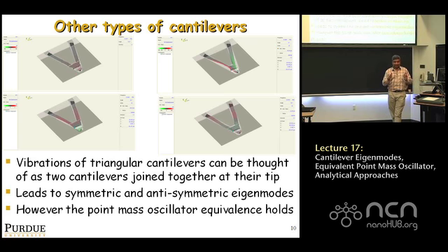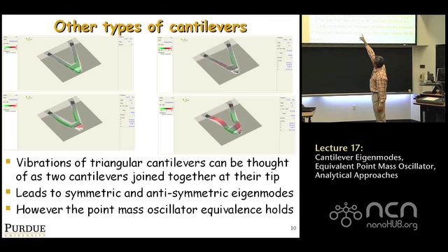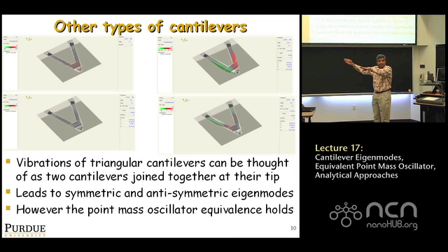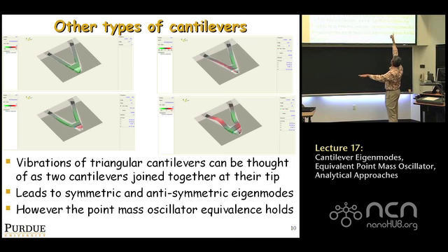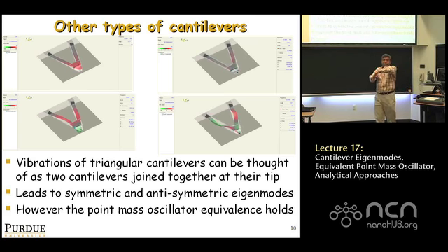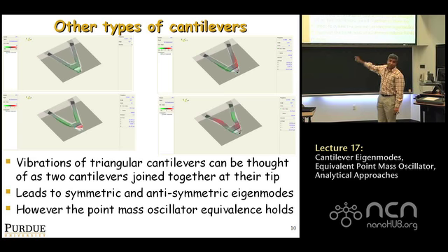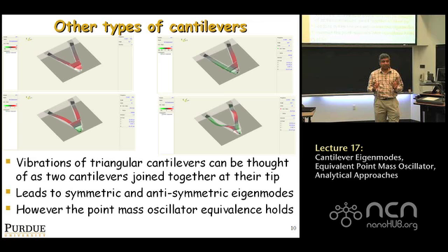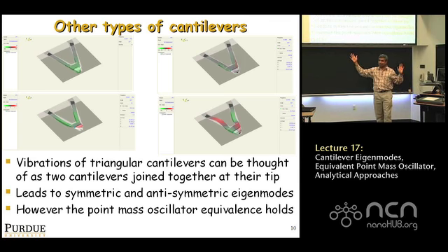It turns out you have this, the first bending mode, where both go up and down. Slightly above that frequency, you have another resonance where they're going out of phase and they're twisting it. So the eigenmode frequency in the top left and the eigenmode frequency in the top right are actually not far from each other. They're pretty close. It's interesting. It's not like very far apart.